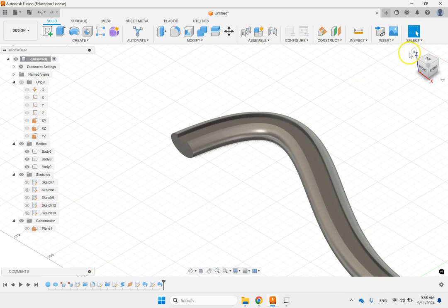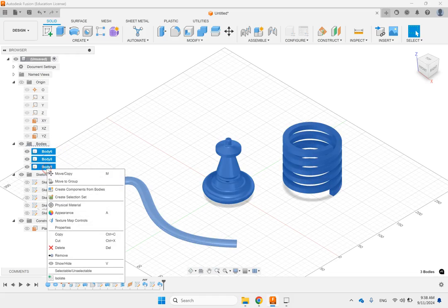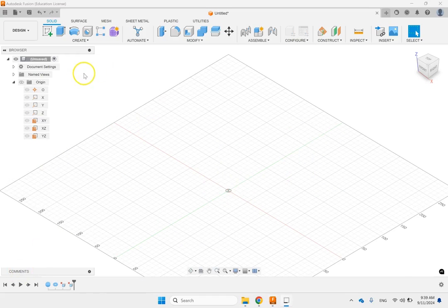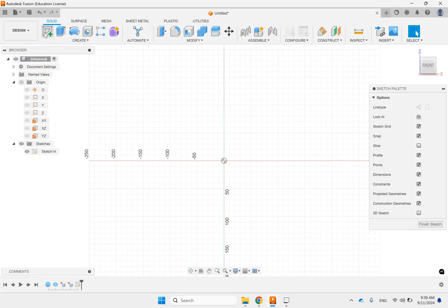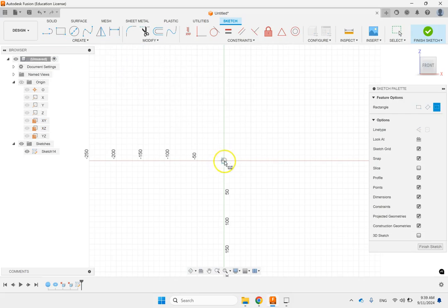Now let's go for loft and cut loft, or you might call it multi-section. So let's go ahead and clean up. Now to do the loft, we need two separate cross sections on two different planes. So let's say we go to the XZ plane, and for instance, we draw a center rectangle, right? So here we go, centered rectangle, and let's draw a square in this case.